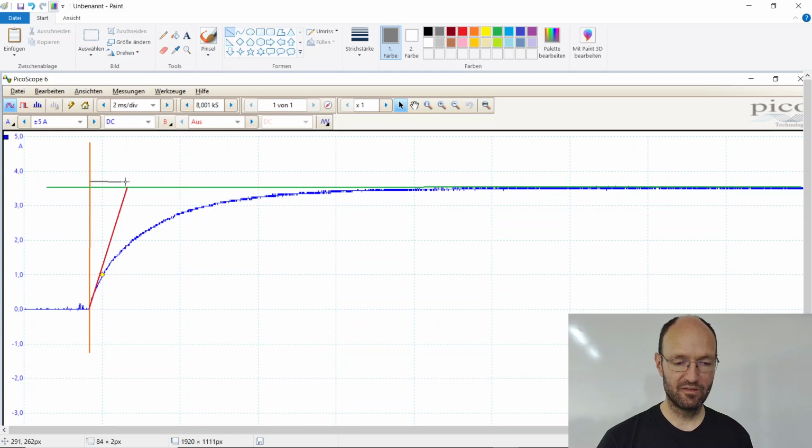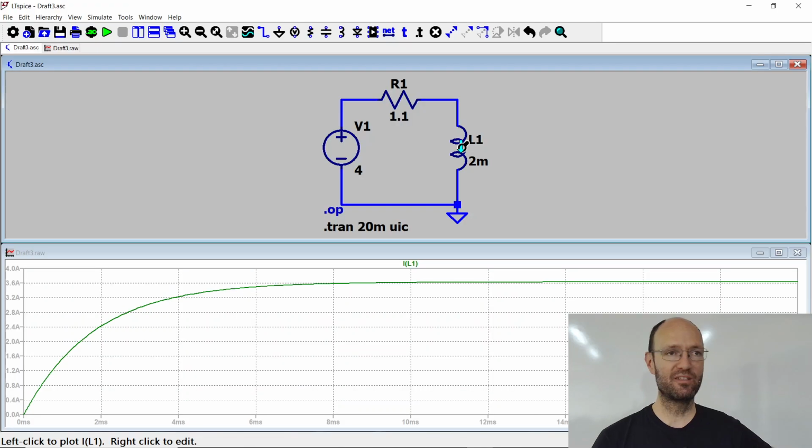Okay, it's still calculating and plotting. The curve is not that steep anymore, and the transient takes more time. And so, at the end, you could just try to fit the motor inductance to your measured curve without calculating the time constant. But in this case, it's quite okay to calculate the time constant, I would guess. Okay, so I will go back to the 1 milli.